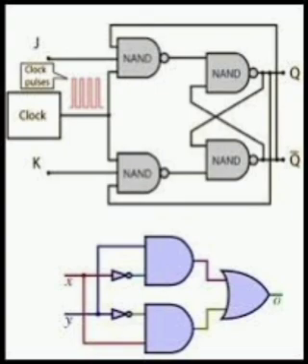Clock 1: SN RN 00 gives QN, SN RN 01 gives 0, SN RN 10 means 1, and 11 means invalid. Here 00 means QN, called the hold state, 01 is the reset state, 10 is the set state, and 11 is a forbidden state. Sn and Rn denote the input and Qn the output during the bit time n. Qn plus 1 denotes the output Q after the clock passes, that is, bit time n plus 1.